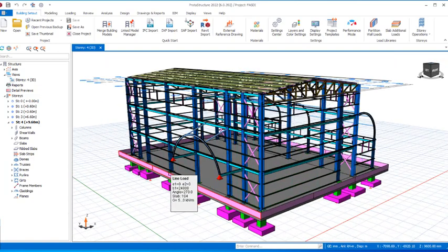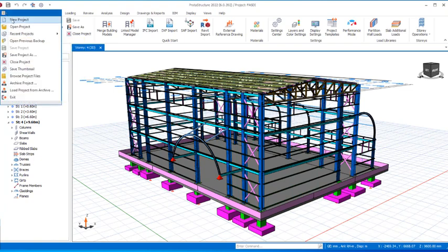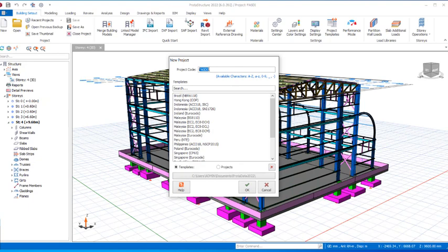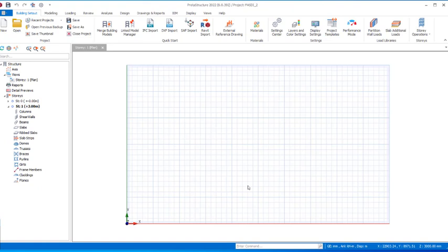So straight away we have to navigate to the new file provision, or you click on this file menu, click on new file. Once you get to these provisions, I will just give it an underscore and key into right there. I will scroll down for my template, United Kingdom Euro Codes template. I will get that selected, click on the OK options. Alright, so the United Kingdom template is created successfully, just like this.